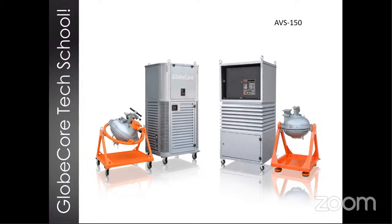The capabilities of the AVS devices are not limited to wastewater purification. It's just something that works really well for the AVS, but there are also other applications. The model range includes the AVSP that is designed to make batches of emulsions or suspensions or uniform mixing of several different ingredients. We can regrind bulk products in suspensions to a particle size of less than 1 micron, so very fine grinding. You can imagine that when these magnetic particles or little metal pellets or cylinders spin around inside that process chamber, that creates conditions for very fine mixing or very fine grinding. So there are a lot of applications of the AVS that can also be of interest industrially. But today we've concentrated on wastewater treatment.